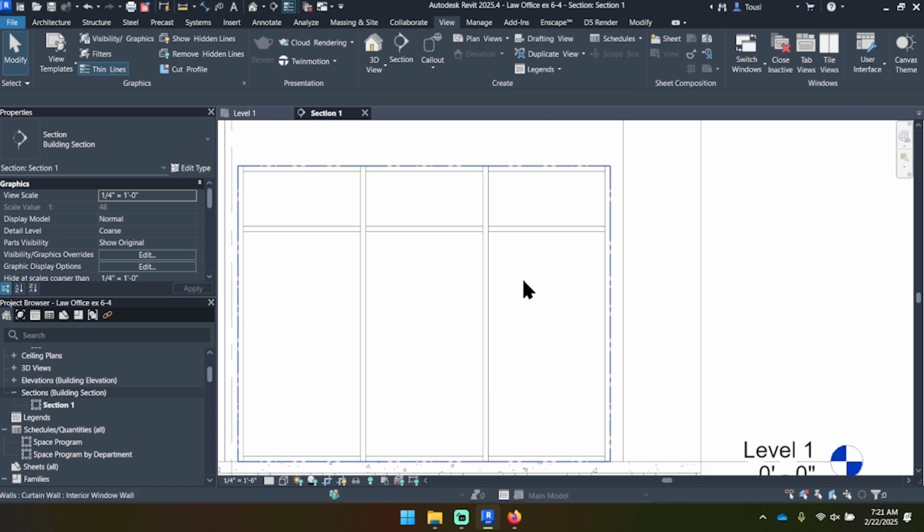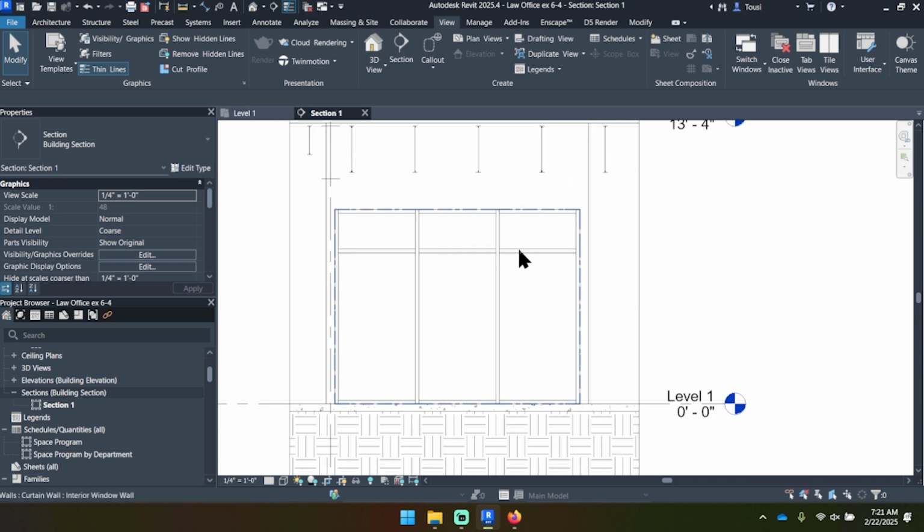So as you can see that we're starting to put together on page 7-15, we're going to need to subdivide this specific panel to be a little bit thinner so that we can add in the door system. But we don't want to just move one of these over, as we're just going to make uneven sizes of glass. So we want to add in one more curtain grid right here.